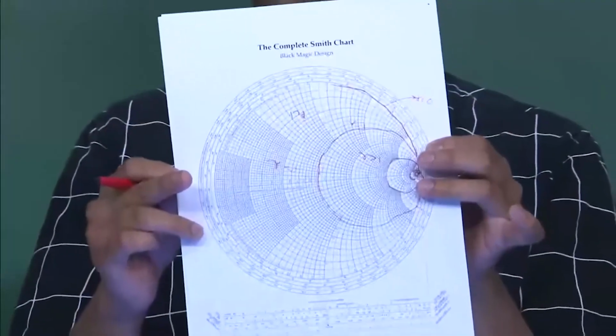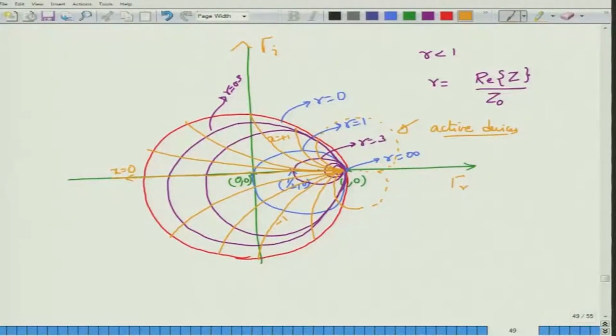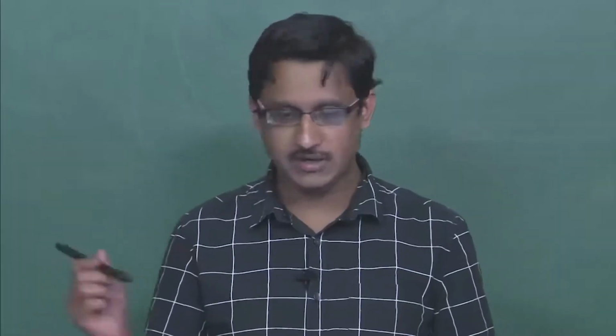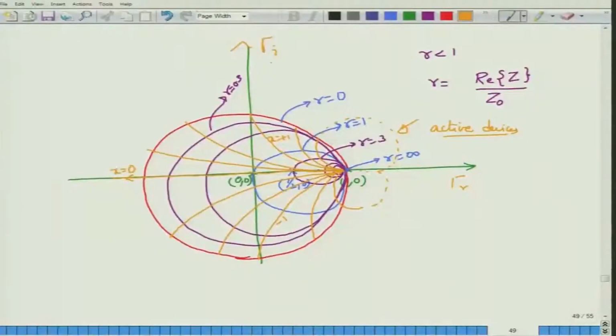Let us come back to the basic use of the Smith chart. How do we use this Smith chart in a very simple sense? As you can see, the Smith chart gives you a relationship between gamma and the complex impedance Z. Please note that I have dropped the normalization bar over here, just for notational convenience, and I have also dropped the function of Z. Clearly the quantities on the left and right hand sides of this expression are functions of the position on the transmission line, but I have dropped it so that it does not clutter our equations.